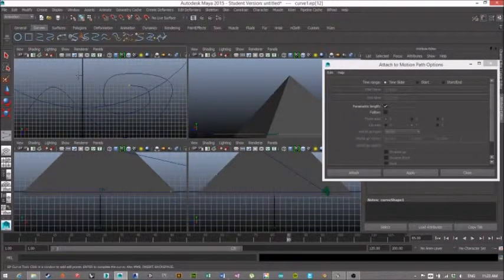Sure, yeah, you select the little aim thing, so if you go camera and aim, you'll see the camera that looks like a camera and then this little icon sticking out at the end. You just select that and then set a keyframe at any frame that you want. So if you're going through a building and you want your camera looking at this wall from frame 1 to 25, you keyframe that at frame 1 to 25. So the camera will still move, it'll stay focused. Then you want it to look over there, you keyframe over there for however many frames and the camera will